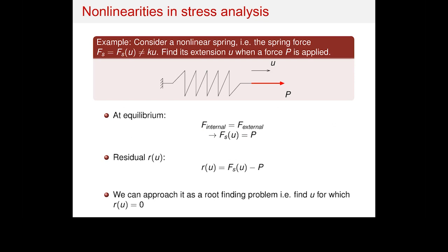All right. As I said, I'm going to strictly talk about a nonlinear case for an elastic material. If you remember from the finite element method, we have the spring to represent the element, and we have the stiffness relation between the force and displacement. You have a force vector, a stiffness matrix, and displacements D1, D2, with entries K11, K12, K21, K22, and then F1 and F2.